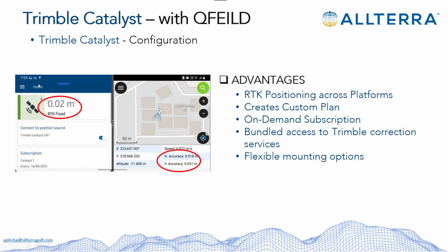As you can see here, as the Trimble Mobile Manager reaches the RTK fixed solution, the same level of accuracy is used in the app as well. So this creates the same information accuracies as an RTK receiver for any of the applications used in the app. So in terms of normal mobile phone location information, which comes in 3 to 5 meters accuracies, now the mobile phone information is turned into centimeter level accuracy.